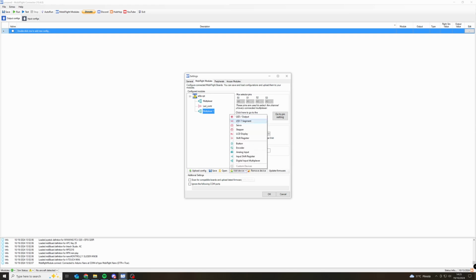The same thing goes for the LED controller. It's a shift register, and here again you just find your latch clock data and select how many bits. In our case it's the 16-bit again, so 2 8-bits, and give the name or don't. It's very simple. What the latch clock and data are again depend where you have plugged them in,